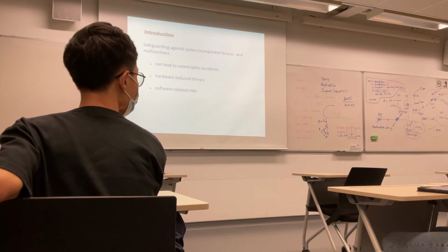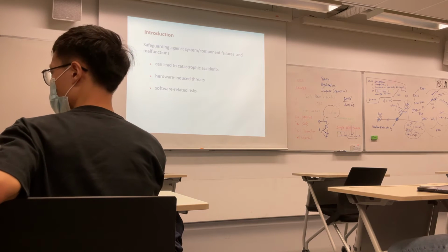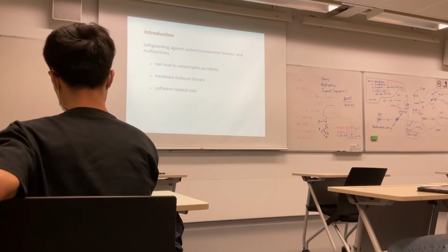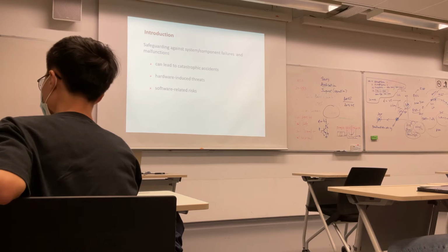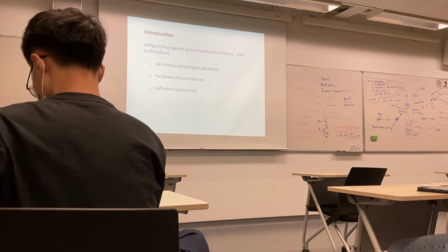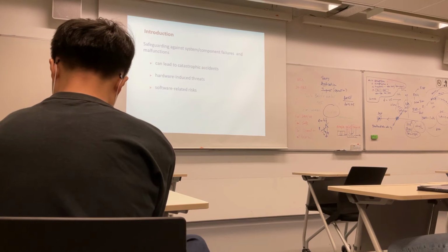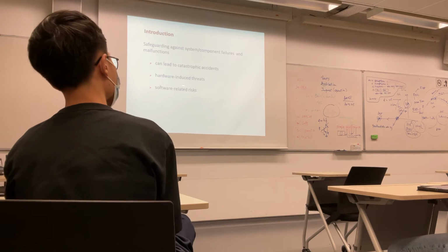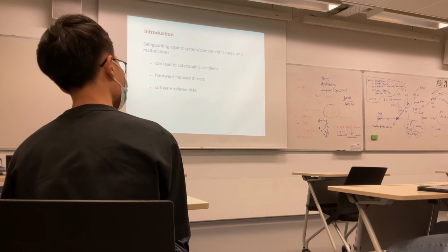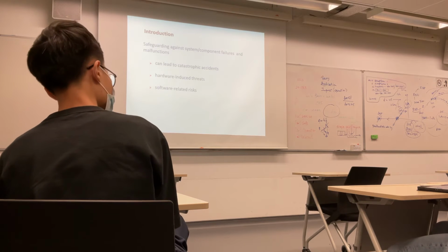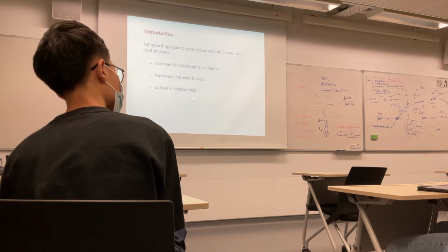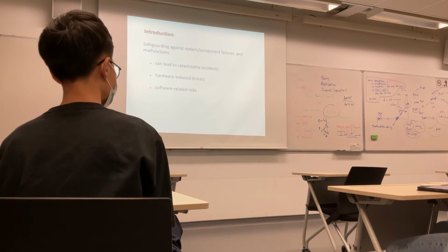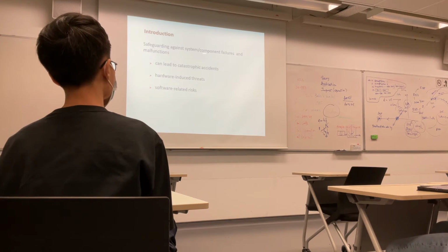The important thing about certifying the software is whether the software can lead to a catastrophic accident. That means a failure of the software can crash an aircraft. That's important. Also whether it has a hardware-induced threat, meaning whether your hardware can actually cause the system to fail, or whether it is software-related. Hardware-related threats include your ESD. EMI is also considered hardware. Software is actually the program itself, meaning the programmer made a mistake or something like that. So these are the kinds of failures.